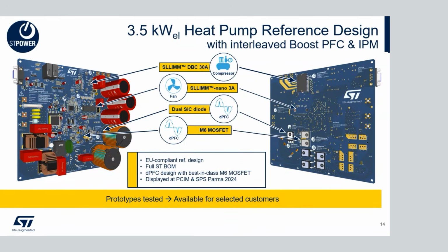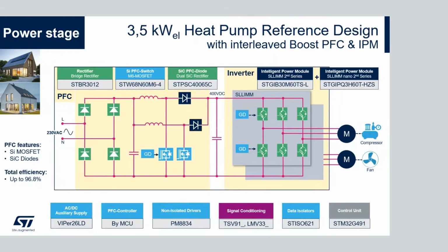And let's now look at the power design of this board, which is what concerns us the most. This is a simplified block diagram, starting on the left with a single-phase input, as mentioned, rectified by, in this case, a standard silicon bridge rectifier, followed by the PFC stage, the dual boost, with silicon superjunction MOSFETs and a dual silicon carbide diode in one package.